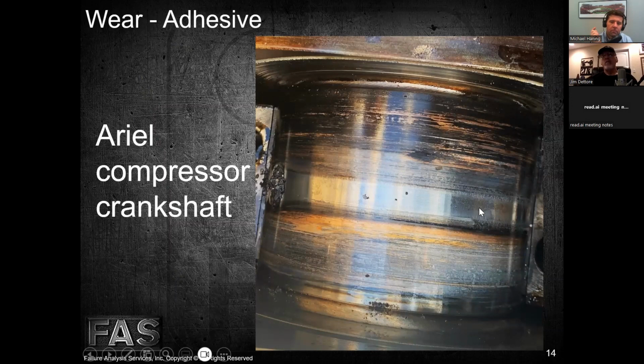And that oil, since this is getting hot and the oil is cool in this area here, it's starting to cause a series of small surface cracks. Can you see those cracks here? Yeah, so almost like quenching that area because it's getting hot and we're hitting it with cool oil and it's expanding rapidly, cooling quickly, expanding rapidly, cooling quickly, and causing all these cracks, which are fairly common to see.